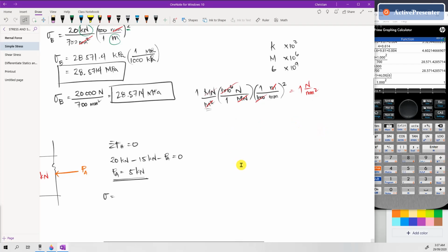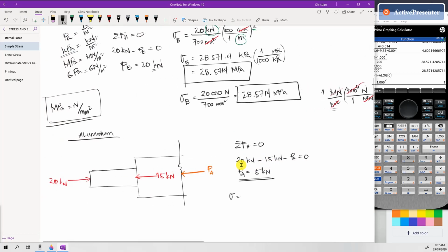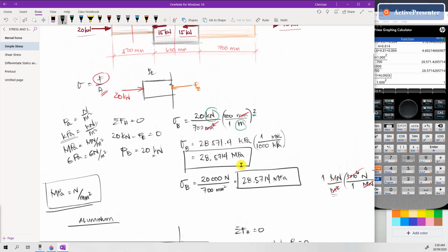So, balik tayo dito. So, solving for, again, stress at the aluminum. Okay, then we have yung 5 kilonewton, gawin natin newton. So, multiplied by 1,000 lang. So, we have 5,000 newton per. So, given naman yung area na 1,000 millimeter squared.